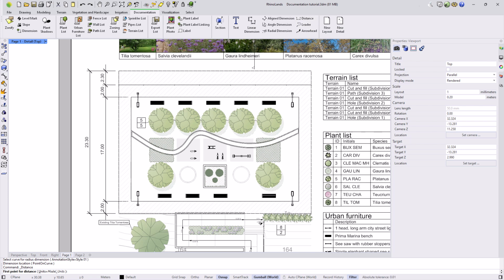The distance tool is not an annotation tool, but a measurement tool. When we want to know the measurement of a distance in the drawing, without needing to create a dimension, we make 2 points in the drawing and the command bar indicates the distance between the 2 points made. The leader tool generates a leader with the path we give it by generating points, with a custom text annotation associated. The last one in this group is the arrow tool, which adds an arrowhead at the end of a selected line.